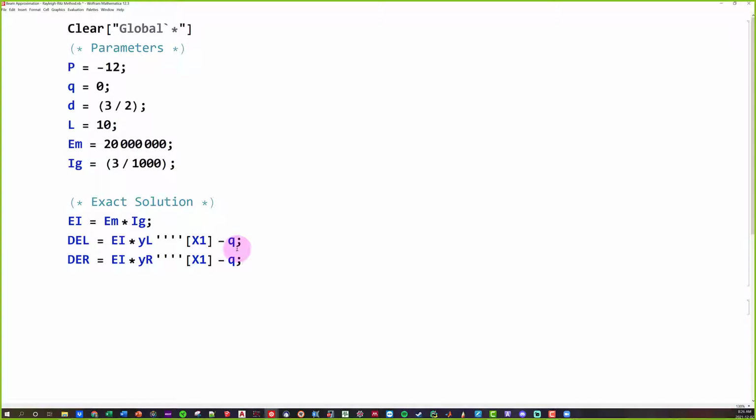From here, it's nice and simple because once we have everything defined, we can go right into solving these two equations. So I'm going to go sol, or my solution, is equal to, and I'm going to use my dsolve function. We've already talked about it quite a bit. So dsolve is basically just the solve function, but the d right here basically means differential. So it's solving a differential equation rather than a linear or nonlinear equation. And inside of the dsolve function, we need three different arguments. So I'm going to separate those with 2 commas.